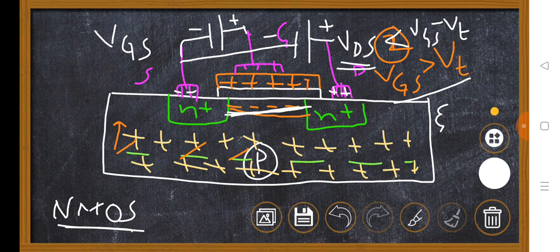There is a slight bend in the channel because if you observe, there is a p-type semiconductor and an n-type semiconductor. Therefore, there is a parasitic p-n junction diode here. Is it clear? If you connect this n-type terminal to the positive terminal of the battery, then which bias is it? Reverse bias. Is it understood? Therefore, the depletion region increases and the channel slightly bends.